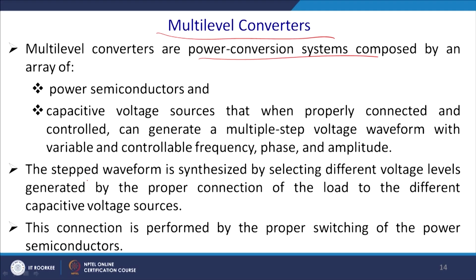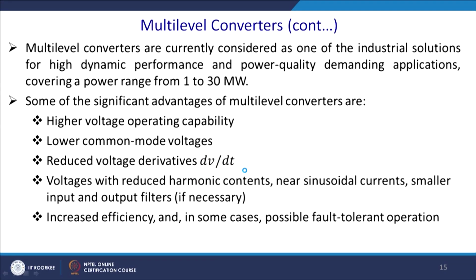The stepped waveform is synthesized by selecting different voltage levels generated by the proper connections of the load to the different capacitive voltage sources. The connection is performed by proper switching of the power semiconductors.